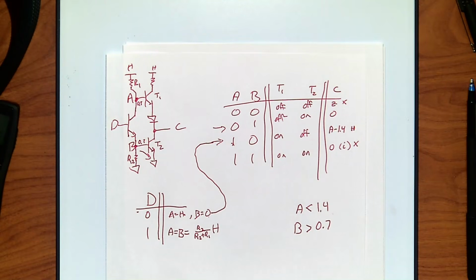Can't do it. So all I do is I usually pick, or you would normally pick that resistor ratio to actually be slightly bigger than 1.4 initially, because it's going to get yanked down really, really fast. So it's irrelevant. And the little bit of extra current actually lets the gate turn on faster.